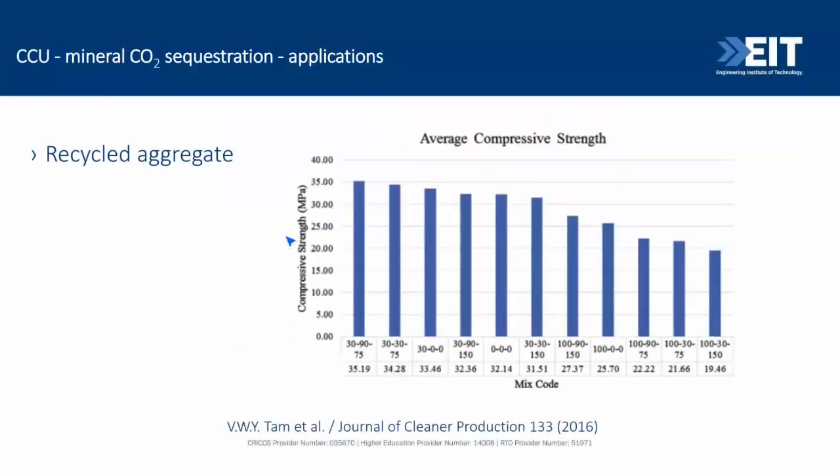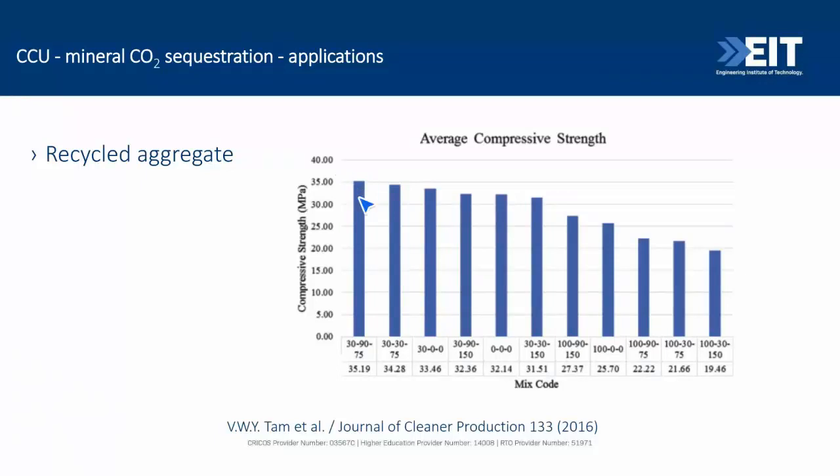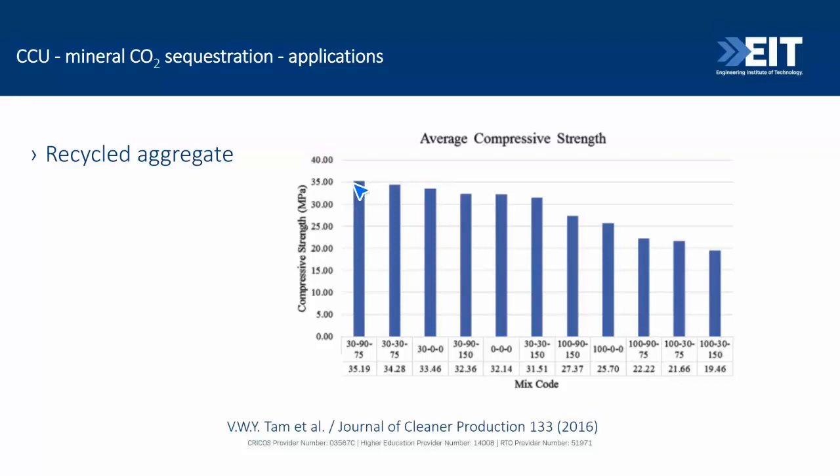So, yeah, but here I'm just going to share some interesting applications. For example, we may discuss the carbonation of recycled aggregates. There are some different results in the literature. Here we have our reference concrete without treatment, and then we can see the compressive strength of the other treated concretes. When the recycled aggregate is treated, it undergoes carbonation. We have the injection of carbon dioxide.